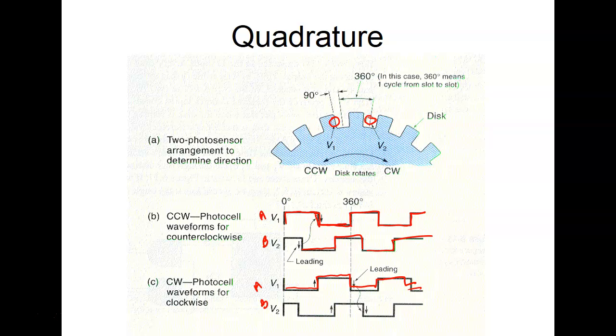So they lost their zero on the back of one of their robots. They call them absolute encoders because they look like they are, but if they were absolute encoders, we wouldn't have to keep batteries on them. So yeah, all these robots have an access panel where you can get to the batteries. The ABB, we had to take off the back of it.